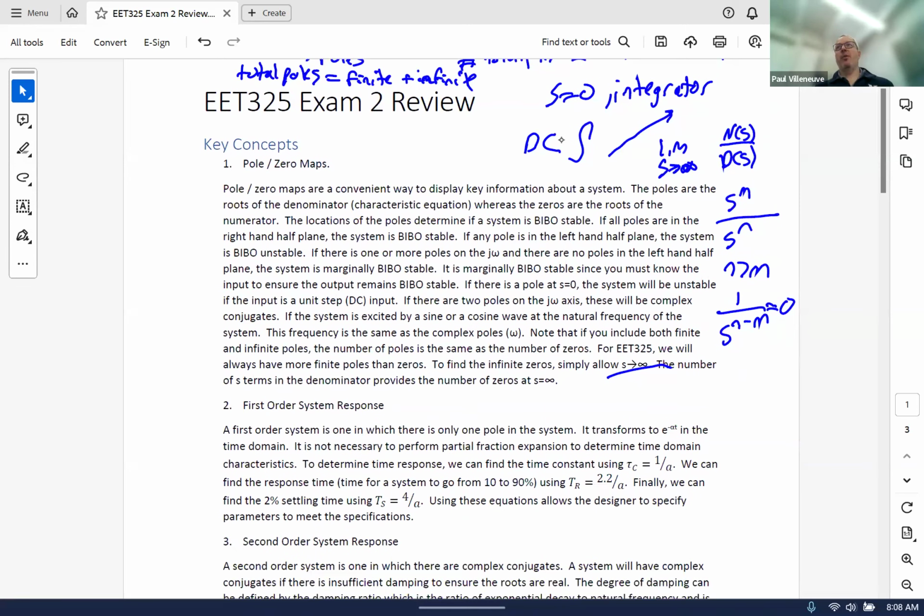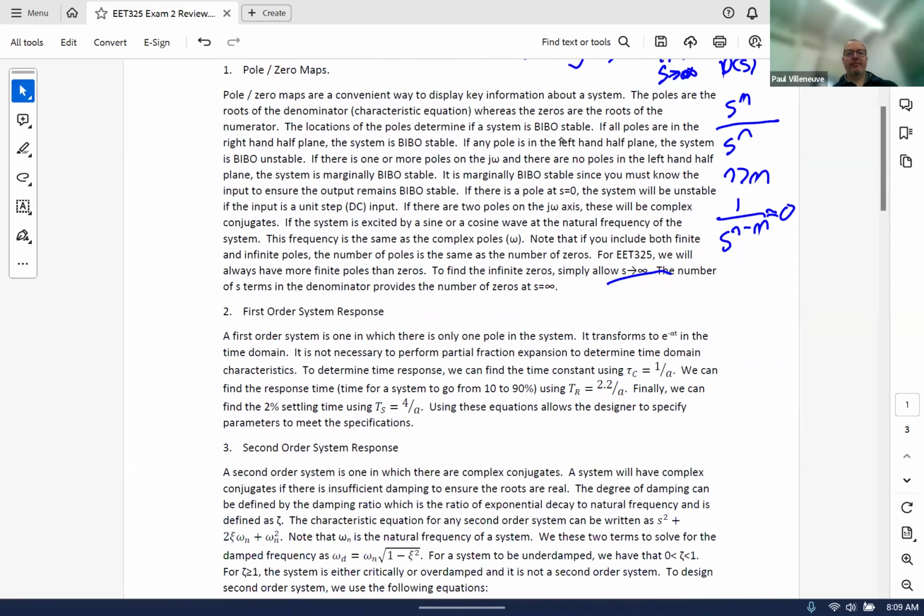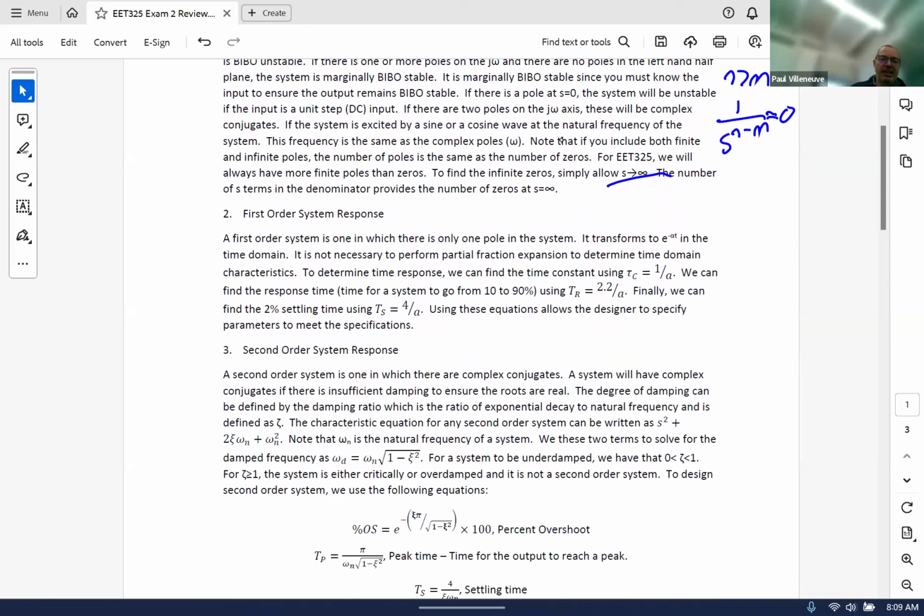Okay, questions on pole zero maps? Make sure you understand that, because it leads well into root locus plots. It also helped us when we looked at Routh-Hurwitz, when we crossed the j omega axis, we used that auxiliary equation, and we started to see a little bit of information about that. As I promised last semester, we did all that partial fraction expansion math, and you had to have your fingernails pulled out to do all that to go back into the time domain. We much prefer to live in the Laplace domain to do all our calculations here.